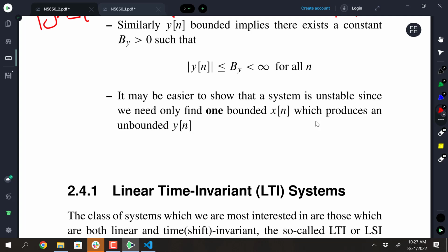So that was a system that was stable, but then under the wind shearing action, it hit a resonance and it caused it to go unstable. And for us in signals and systems, if we have a system that's marginally stable, and we'll run into this in the next chapter, we might have a pole at z equal to 1, so it's right on the unit circle, and if a second pole hits that system, namely due to the input from an impulse response, it will change the system's output.